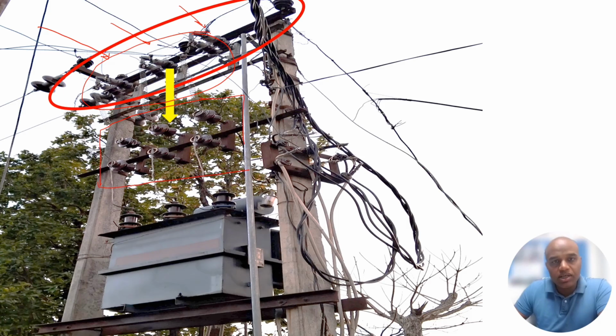And what is being shown here is these spiral windings coming and connected to the insulators over here. The three phases are coming like this, and then from this insulator to this insulator a comparatively thin wire is connected in this fashion, and then from here the incoming wires are connected to the high voltage bushing side of the transformer.